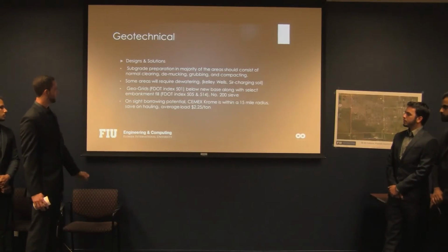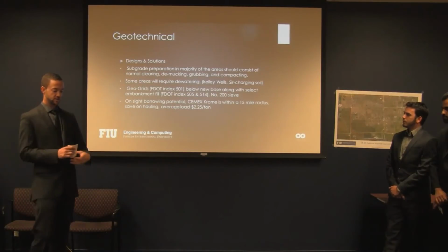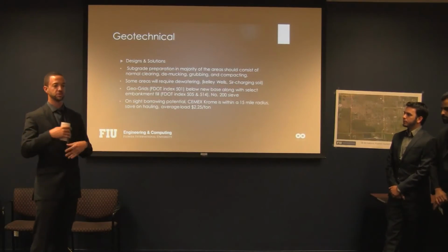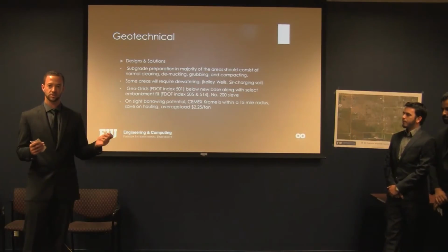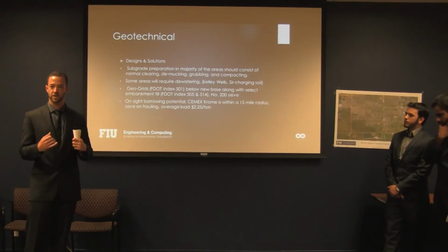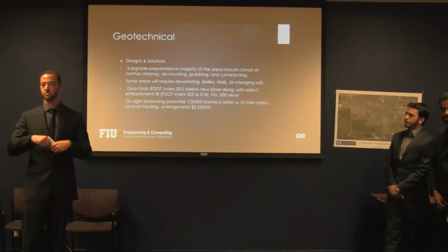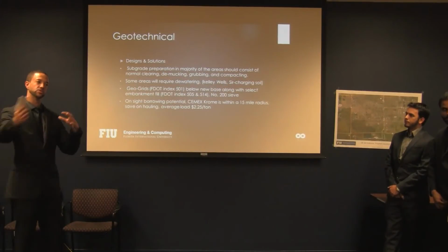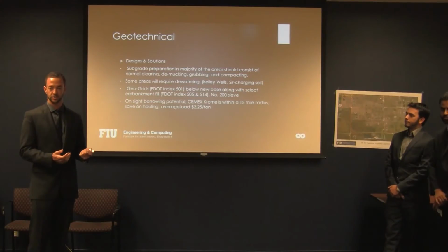FDOT Index 505 and 514 with the number 200 sieves. And on side borrowing potential, we would try to do as much side borrowing as possible. We're also right next to CEMEX Chrome, and that was actually a pro for us because that cuts down on a lot of costs, because hauling limestone for your foundation to your actual job site does add up.